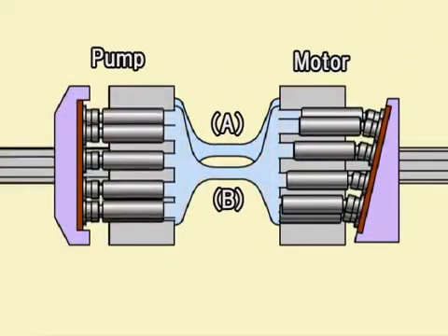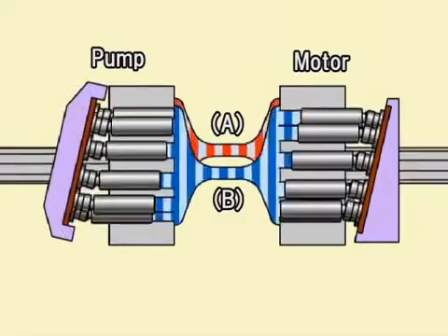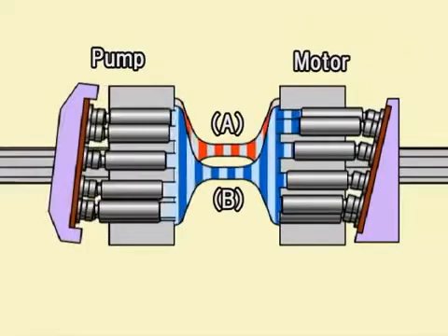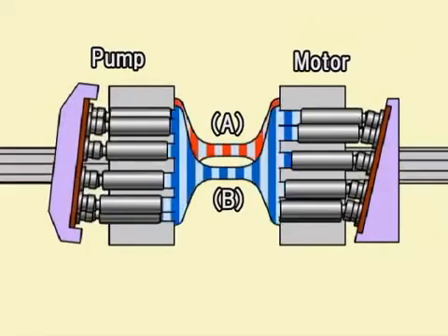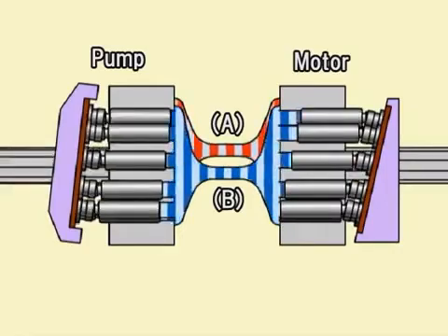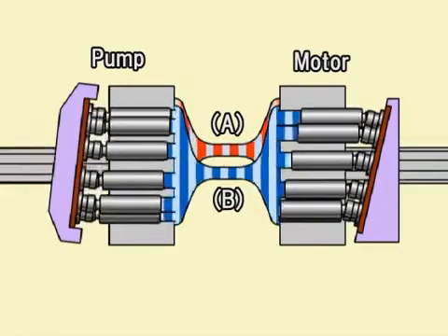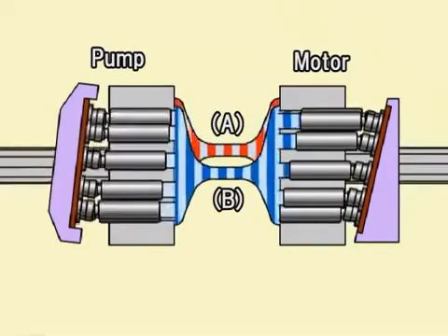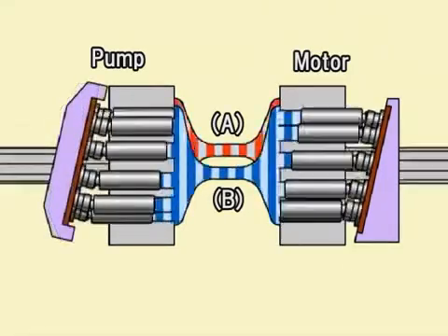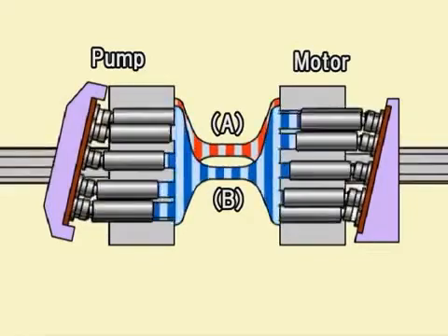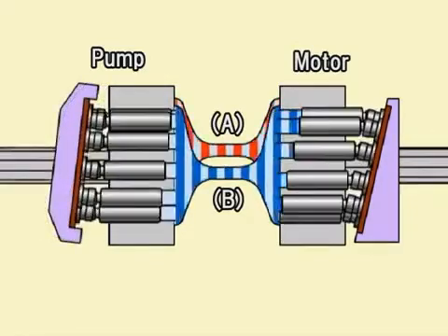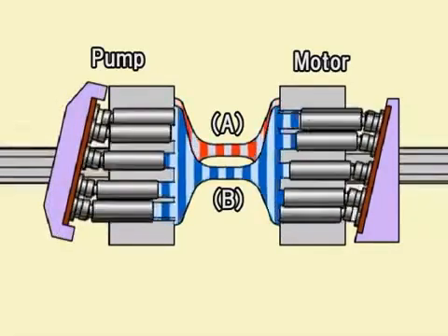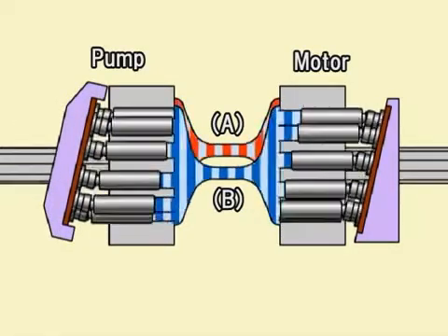The distance the pump pistons move in the cylinder block, and thus the volume of oil pushed out, is controlled by the angle of the variable swash plate. This means that the machine speed changes depending on the angle of the variable swash plate. Increasing the inclination increases the machine speed, while reducing the inclination reduces the machine speed. Thus, using just the speed change lever to control the inclination of the HST swash plate, an operator can control the output shaft speed and rotational direction and move the machine forward or backward at a selected speed.